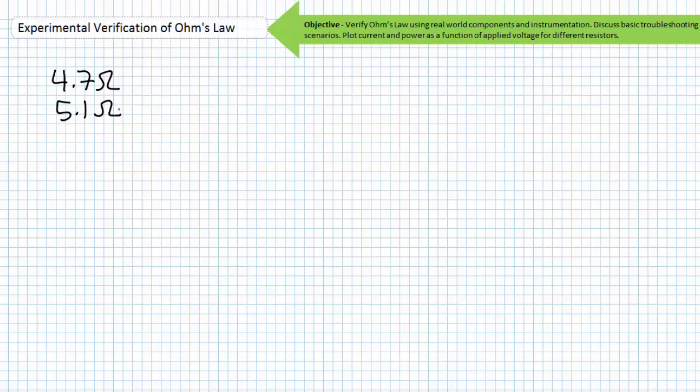Did you back the winner? The dead giveaway is the physical size of the two resistors. Yes, I know 4.7 ohms is smaller than 5.1 ohms, but it's clearly a physically larger resistor and obviously has a larger power dissipation rating. These two resistors have relatively close resistance values, but have totally different power ratings as indicated by their physical size.